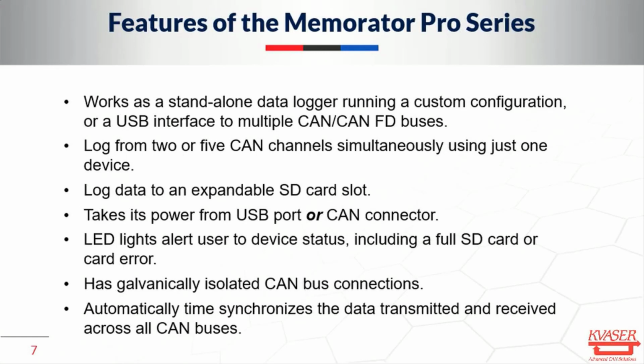Power from the CAN connector is obviously required when they're in a standalone logging application. When I say a standalone logging application, I mean you configure these devices, you disconnect the USB port, you ship them to somebody, you plug them into a vehicle, you send that vehicle out, and they're logging data independently according to that configuration.